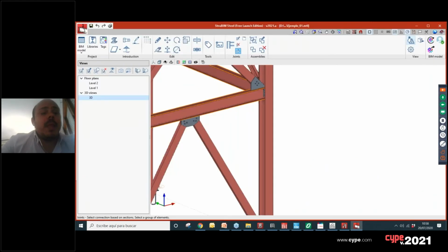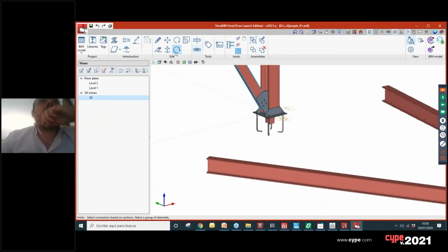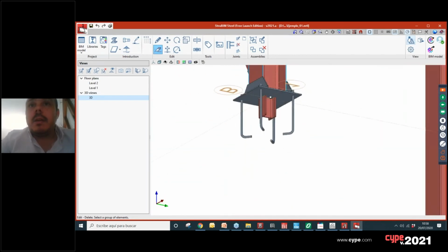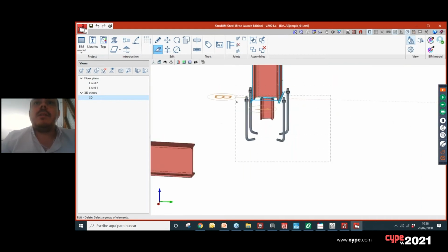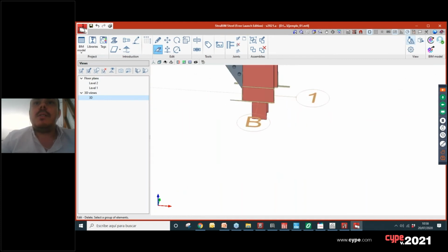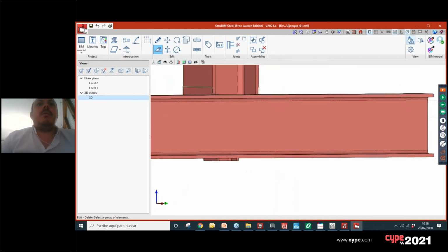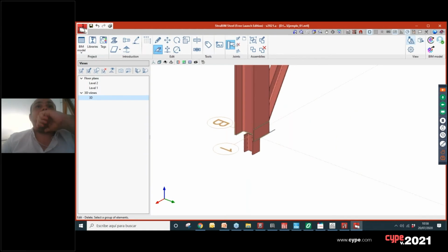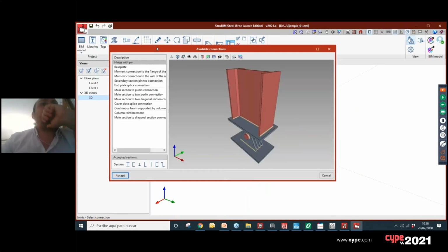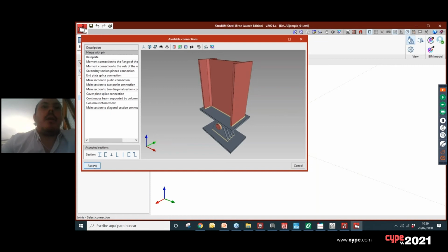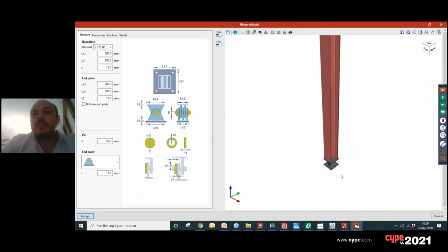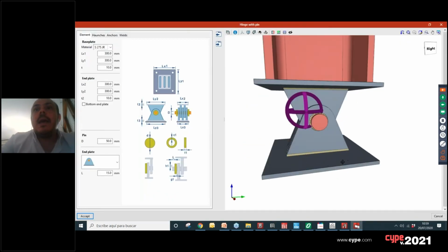Okay, and for example, I'll do another one. I'll erase another one here. Let's erase these elements here, all these elements here. I think it's okay. It would be better if we erase everything, but it's okay. I can go to, for example, our list of connections and use this hinge with pin here. And I will find the node here, and we can add this element here.